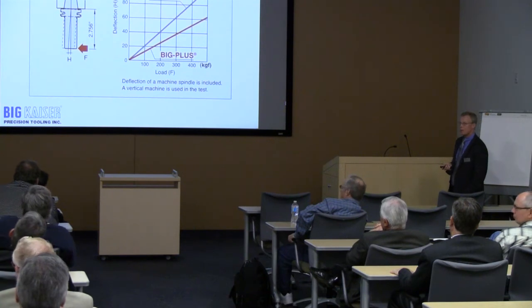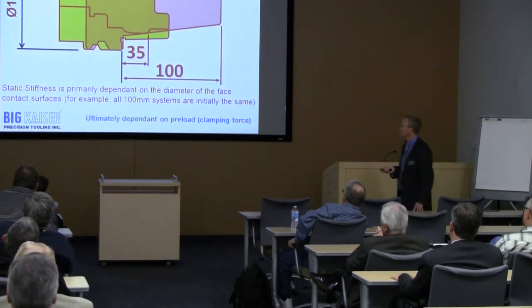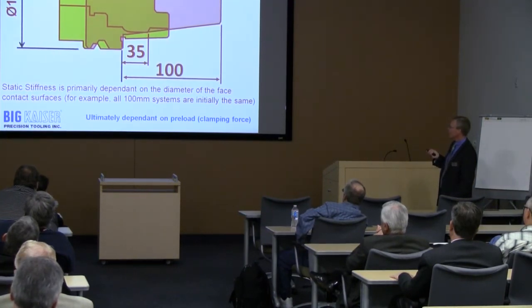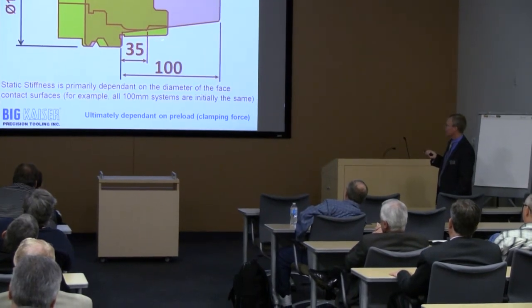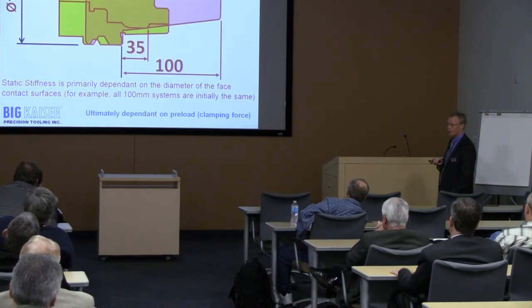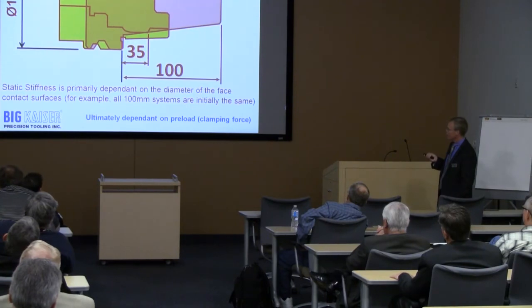Question. Yes, sir. That last line, the HSK, how come it's only part of the taper that's engaged? The drive keys of the spindle are released, so if I look at my spindle, it's released back here. There's no taper contact in the spindle from that point forward. These drive keys and all that, if you look at the spindle, if I was drawing that in there, you'd see it's cleared out here. Okay?